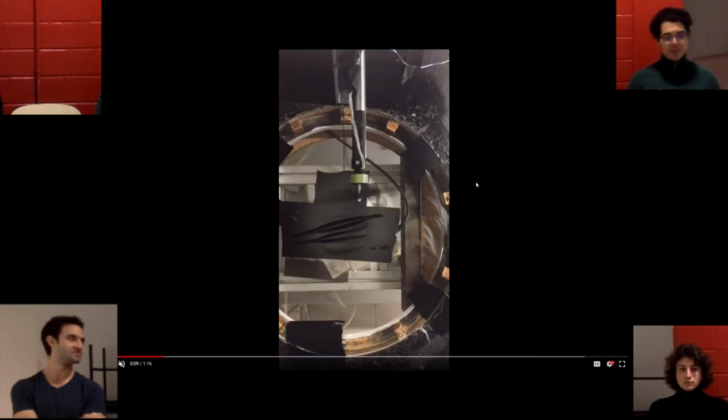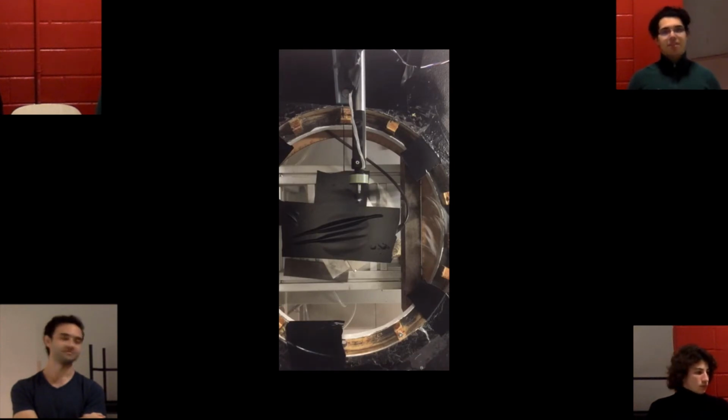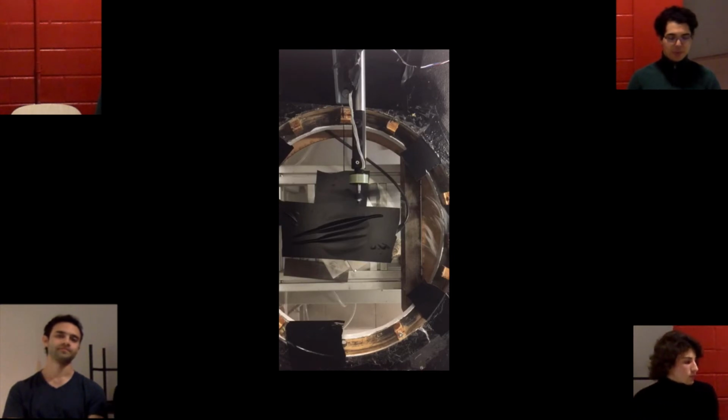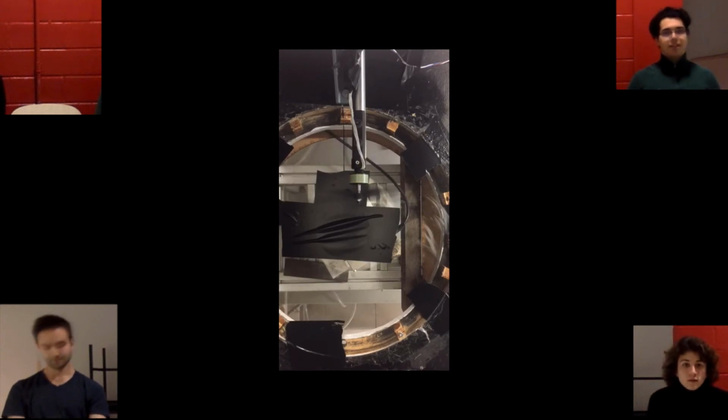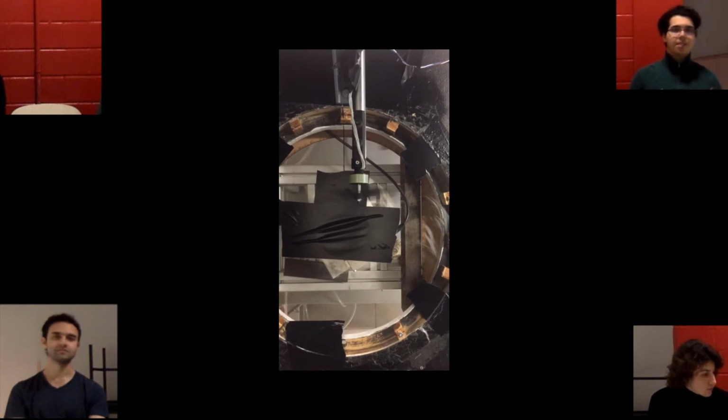So in this video, we can see the propeller actually functioning in the air tunnel. So in this test, we can see fairly well certain misalignment in the mounting of the propeller. We're thinking that this probably induced more noise and vibrations than would otherwise have occurred in the propeller, which obviously affects efficiency and the ability of the thruster to work without causing noise in the thrust curve, which is reflected in our results.